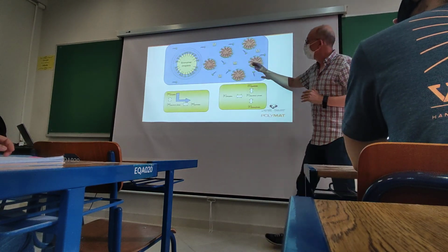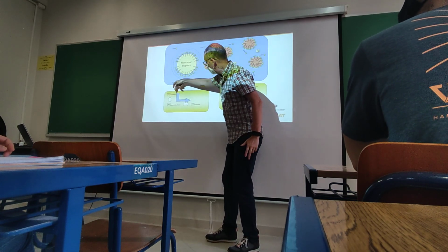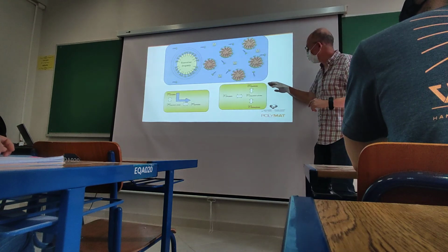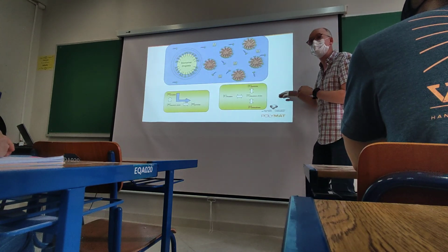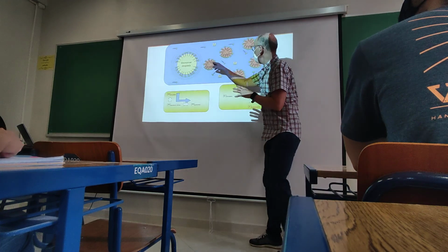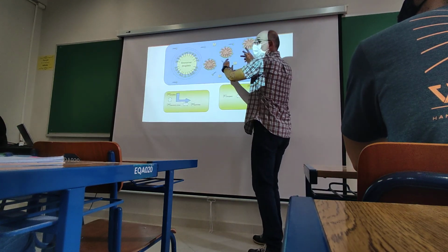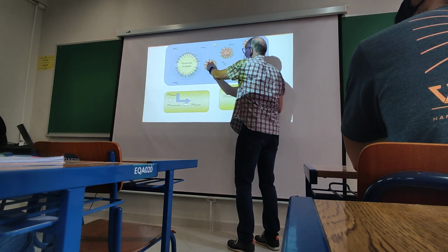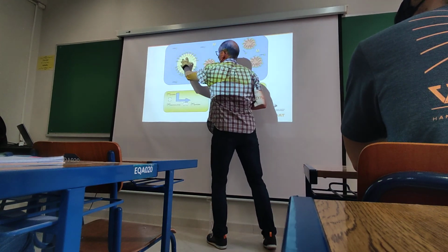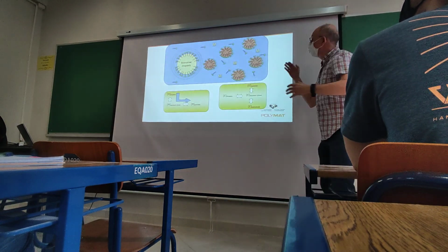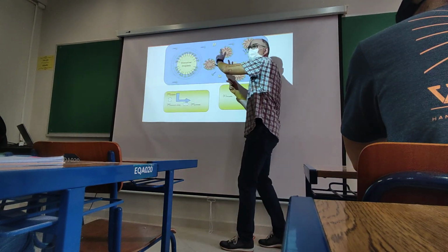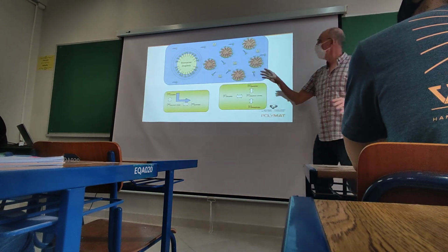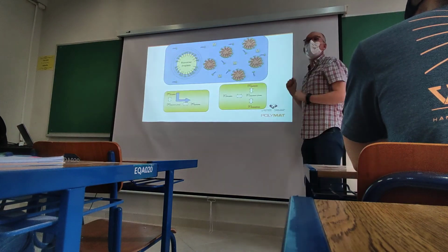In the second interval, we now have monomer in droplets, aqueous phase, and particles, no micelles. And the same for the surfactant: it is not anymore in micelles. So the polymerization continues here. Radicals enter into the polymer particles, and monomer is transported to the polymer particles. So the polymer particles grow, the droplets shrink, and the process will continue in this second interval until we run out of monomer droplets. So droplets disappear, and we have particles which are growing.